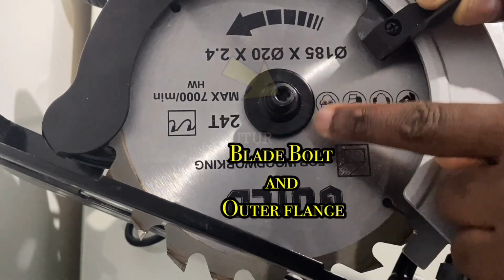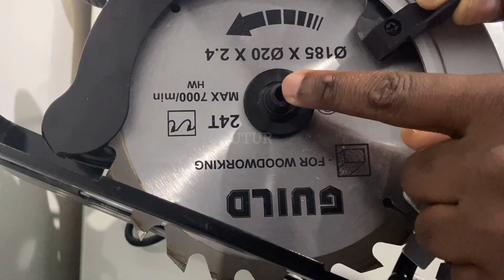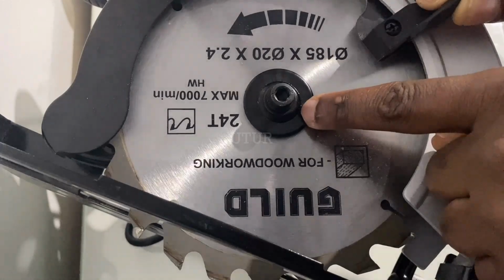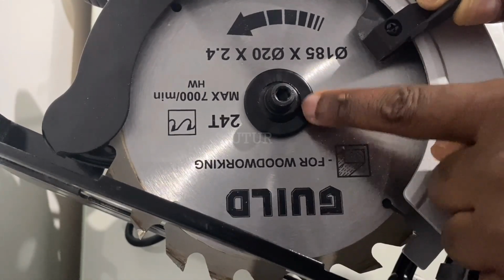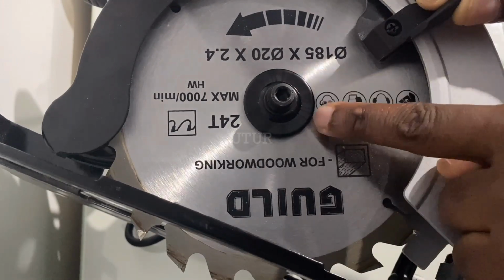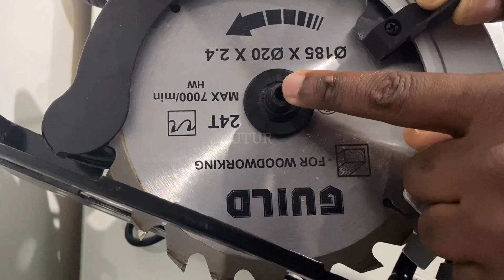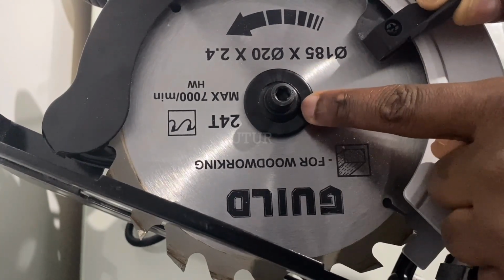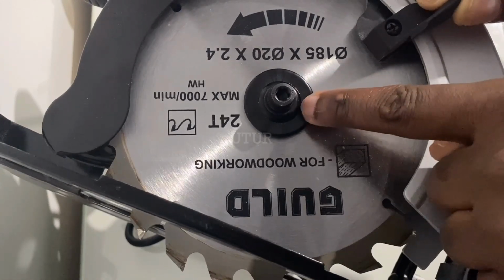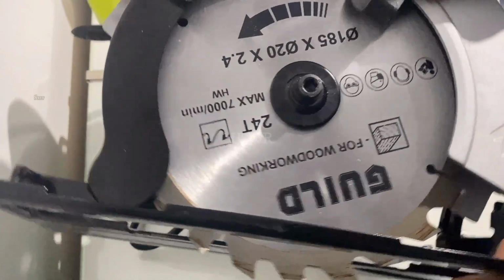To change your saw blade, you need to take out the blade bolt and the outer flange with an Allen key, which then reveals the blade bore, the saw blade, and an inner flange behind it. Just remember that when fitting in a new blade, the saw blade must be sat on the inner flange, okay? Suffice to say, the saw blade must be sandwiched between the inner and outer flange, with the blade bolt coupled onto the outer flange, okay?